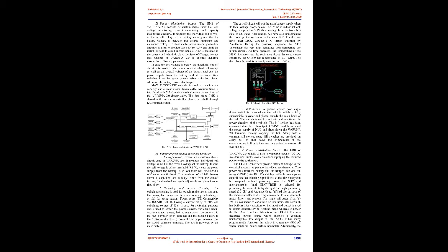C. Kill switch. A generic double-pole single-throw switch is mounted on the vehicle, which is fully submersible in water and placed outside the main body of the hull. The switch is used to activate and deactivate the power circuitry of the vehicle. The kill switch has been connected directly to the output of the PDB and thus controls the power supply of the NUC and shuts down the VARUNA 2.0 thrusters, thereby stopping the bot, along with a common kill switch. Spare kill switches are provided on every hull to shut down the components of the corresponding hull only, thus ensuring extensive control all over the bot.